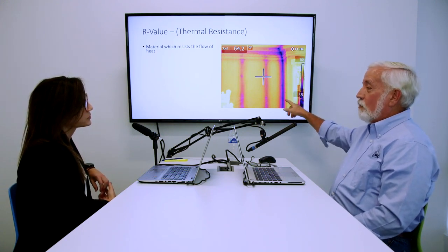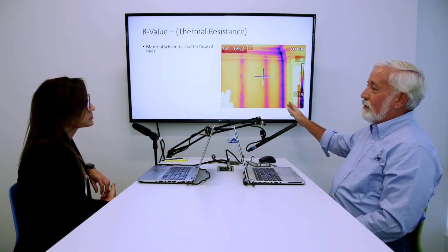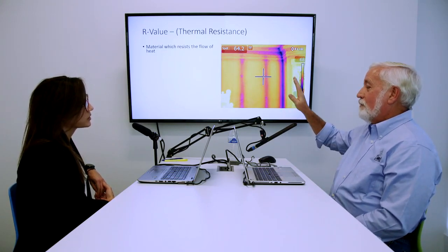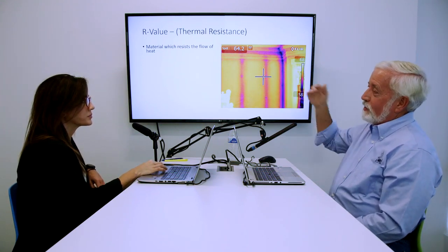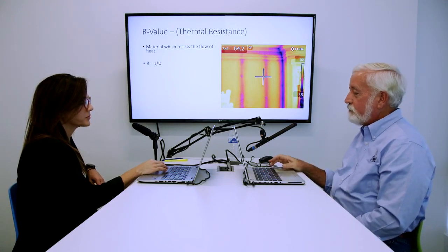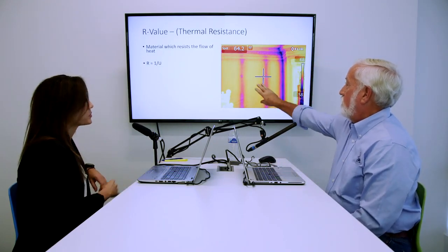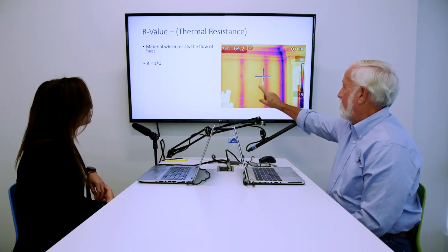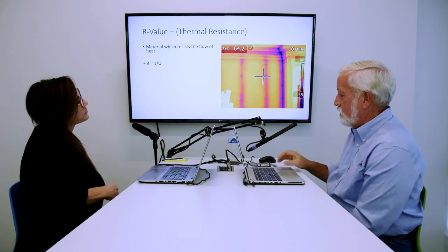And so it's 10 degrees colder because we're losing heat at a greater rate, or we have a heat flow because we don't have what? We don't have any R value to resist the flow of heat. Right. So if we can do something to minimize the heat flow, what do we do? We reduce our energy consumption. So R value is whatever resists the flow. We have good R value here, so it resists the flow. We have less R value here, so less resistance. Where the metal screws are that go part way in the stud, even less. And where we have no insulation, we have even less.